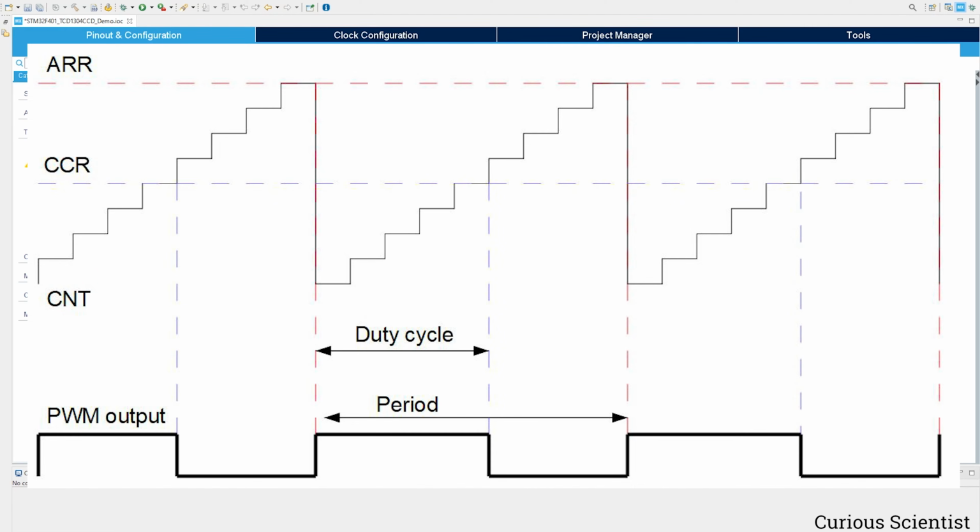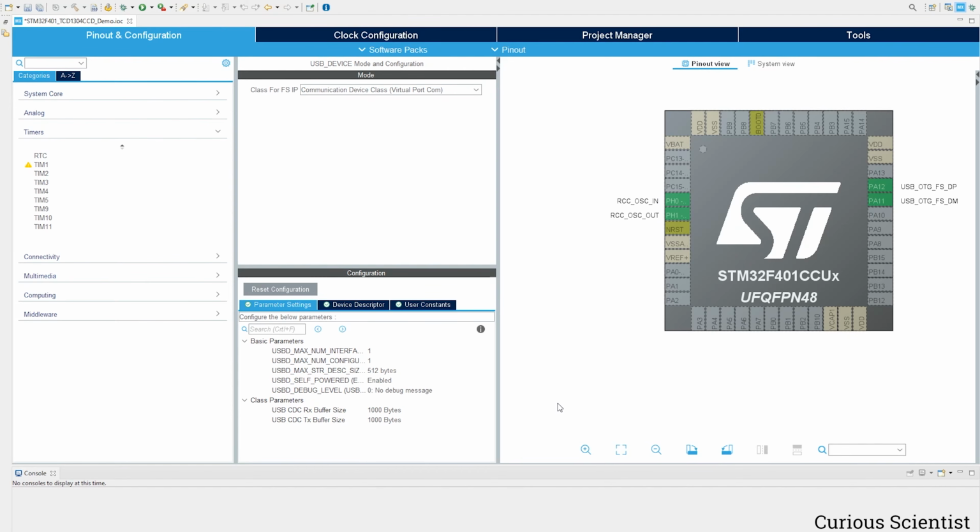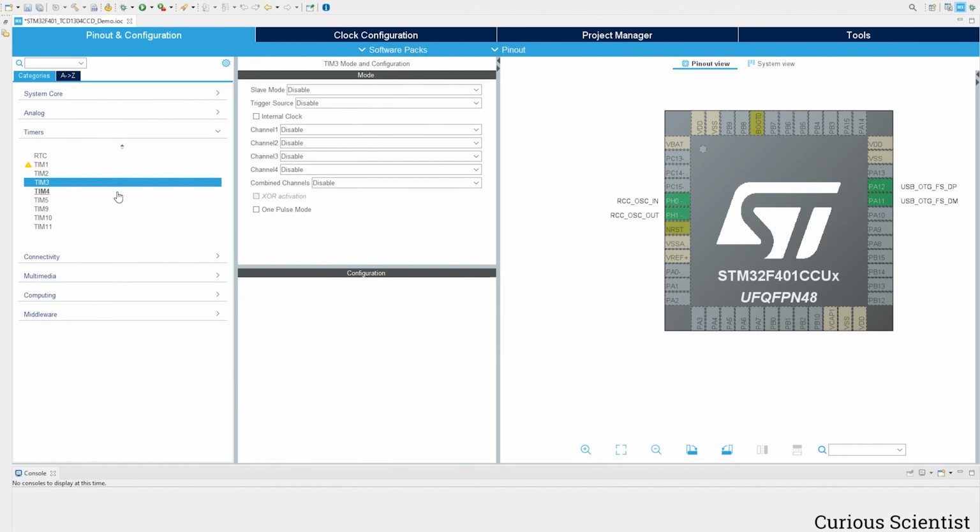So the CCD is driven by 3 PWM signals, and we have to know how we manipulate the PWM signals, their period and their duty cycle, with these timers, so we can drive the CCD properly. So now we can start with the simple timers, so the 16-bit timers, timer 3 and timer 4. I would like to start with timer 3, and that will generate us the main clock, the 2 MHz clock.